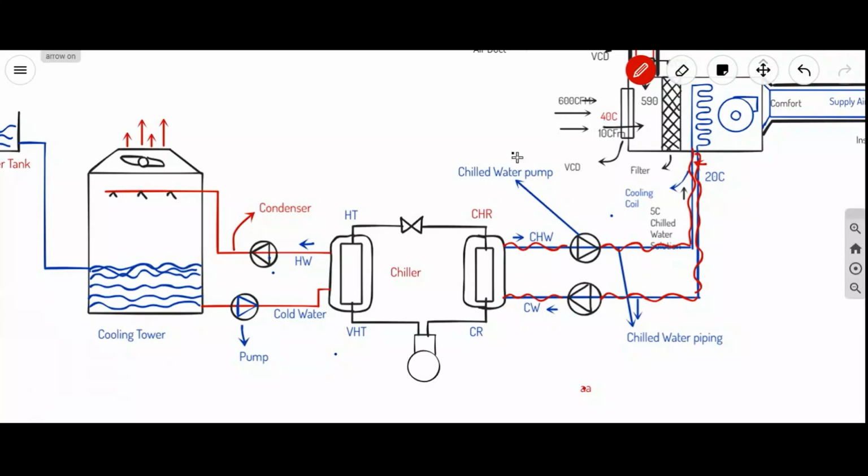Are we using only water there, or any other solution? Somewhere I saw that they are using a brine solution, glycol, methanol, different types of solutions depending on the temperature. We calculate this: if it is less than 4 degrees centigrade, we use a brine solution. Why? At 0 degrees centigrade, the water freezes, right?